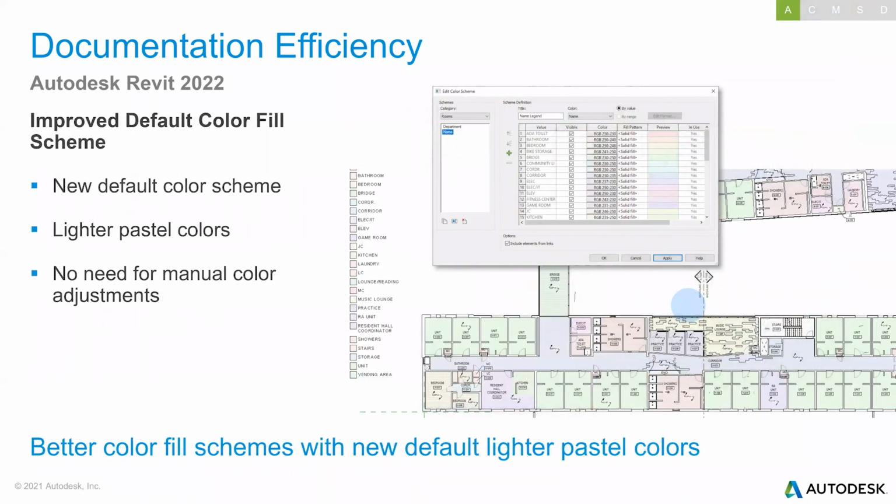And while we're on the topic of coloring our model and views, the default color fill in those color fill schemes has now been greatly improved. I'm sure anybody who has used the color fill scheme in the past has cringed at the bold, harsh, strong colors that they defaulted to. They've now been done away with, and they now put in a much lighter and pastel color as a starting point. Now, you don't necessarily have to like the colors that they choose, but it certainly looks a lot better than those harsher colors that they previously had.